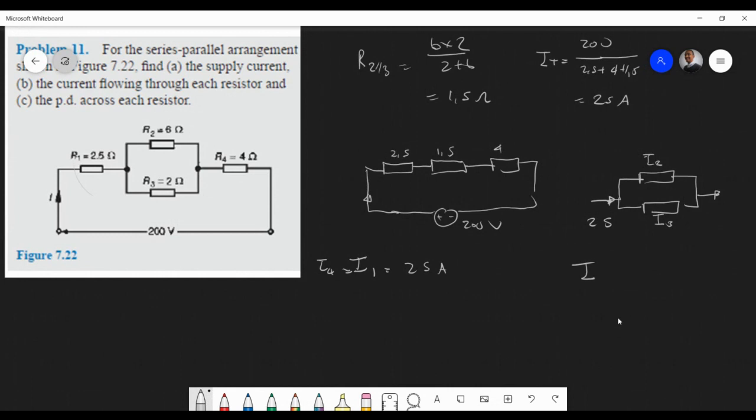So we're using current division. For us to find I2, what did I say we must do? Take the current source and times by which one? What do we times by? The one that we don't want. 100%, the one we don't want. Exactly. I've got a bunch of excellent students here. So that's times 2, and then it'll be over 2 plus 6.